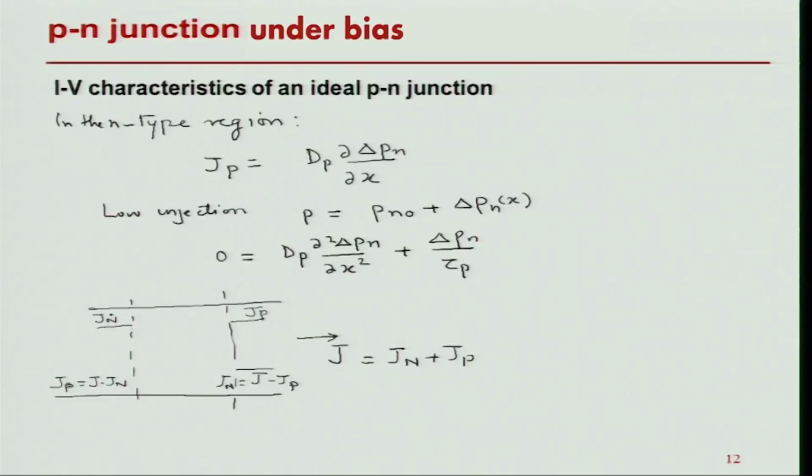Okay. So, what we have done is we have written an expression for calculating this, and we have written an expression for calculating this. And we do not know exactly how it will go on in this, we can try to figure that out. Now, this might look weird because we have kind of ignored the depletion region, which is not surprising, because what we have assumed is a low injection, and throughout our qualitative description we said, well, there is nothing much changing in the depletion region in terms of the balance.